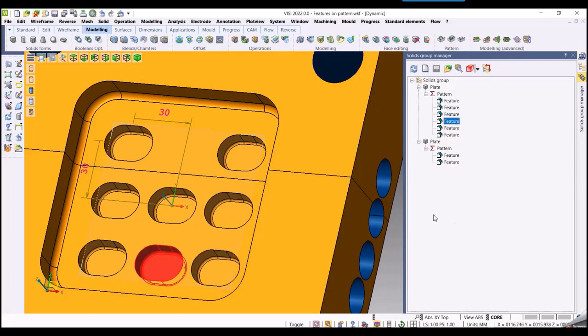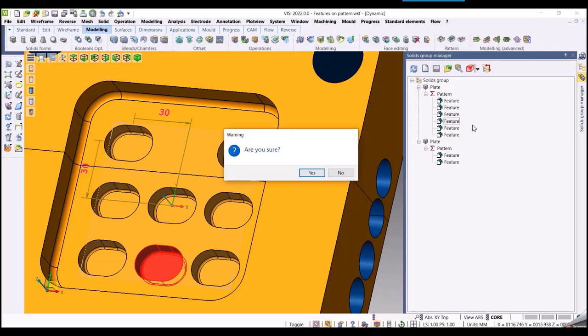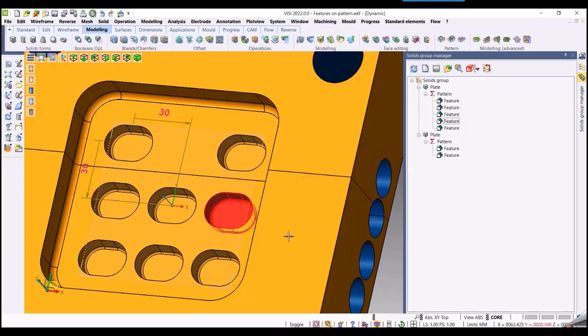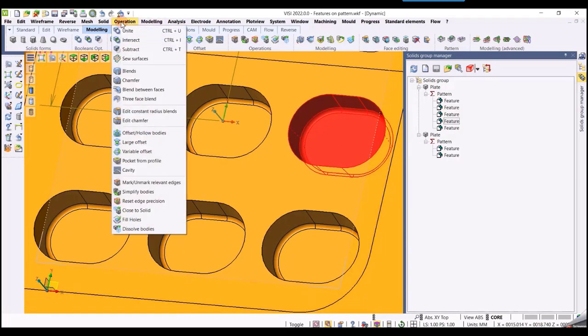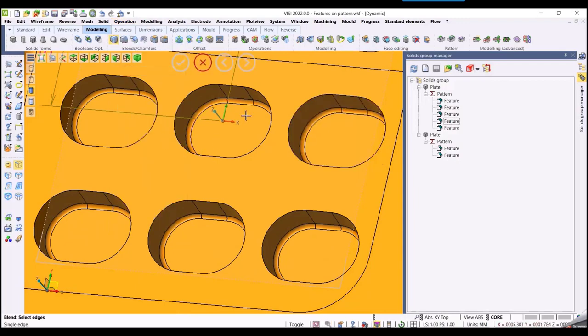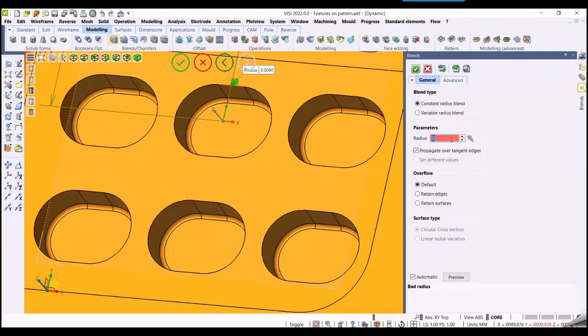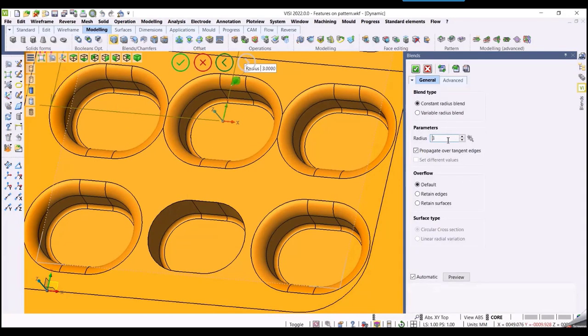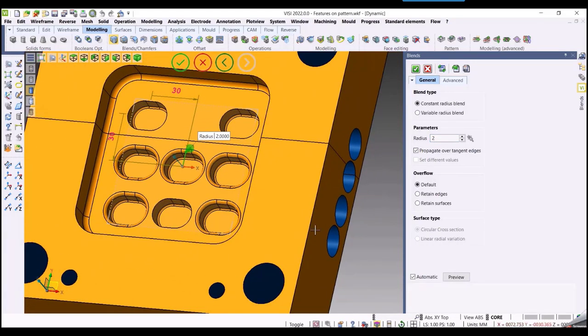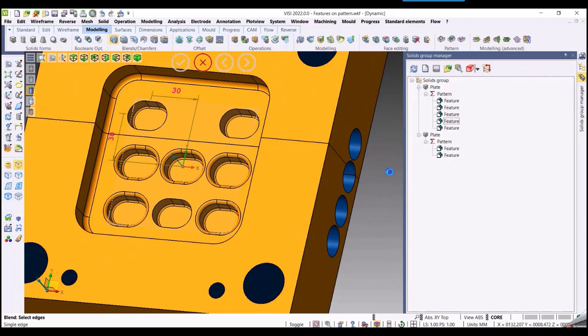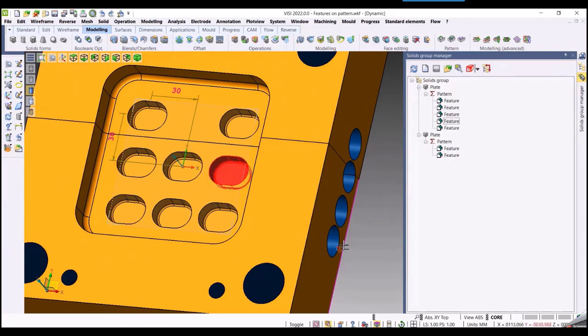So you can see how it automatically separated out those bodies via a cut body. And if I unlink this one, for example, and I make a modification, it's not going to include the modification on the bodies that were cut, and it's not going to include a modification to the one that we unlinked, but it will include the modification on the others as well. So it's remembering the create instance, and it's doing it on all of those other ones, but it doesn't retain it on the separate body that was split, and so on.